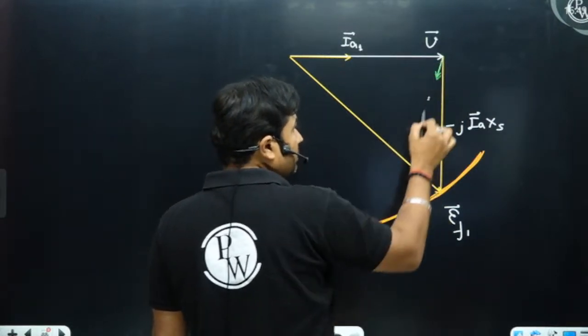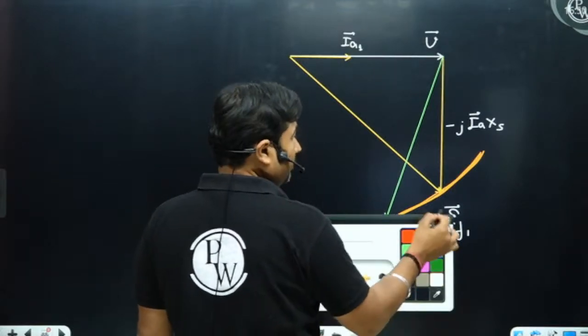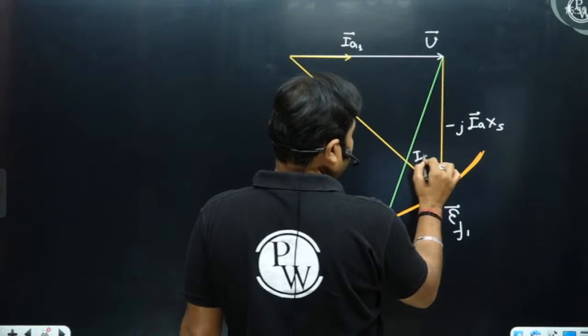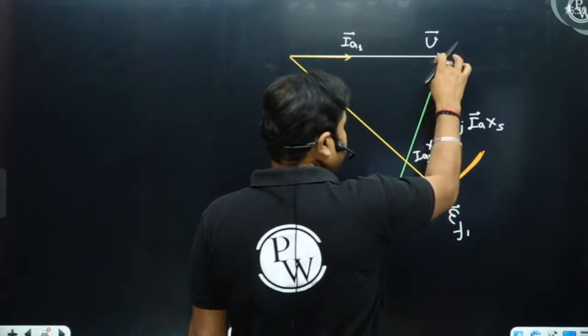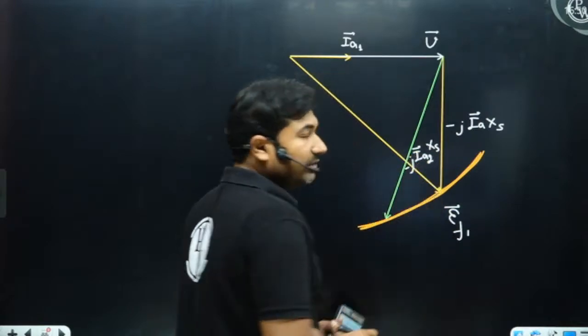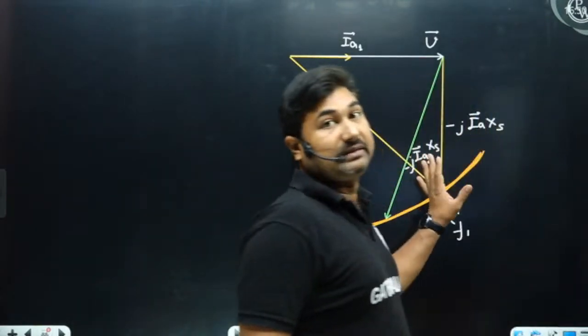So when the motor draws a current of 120 ampere, it means definitely the load is increased, because then only the current will increase. So this will be your new j IA2 Xs axis. For phasor you may represent like this. However, in a phasor diagram we never represent the j term, but I am representing it just to show you the equation.